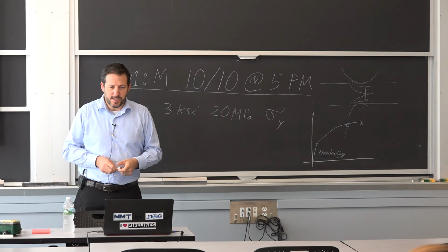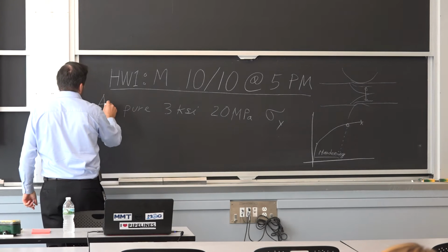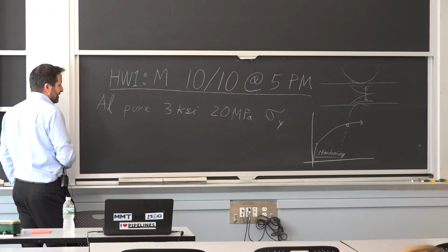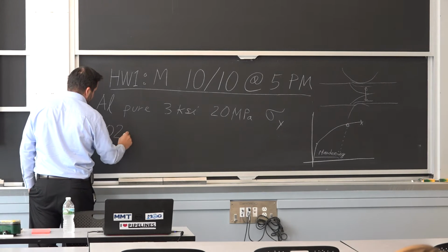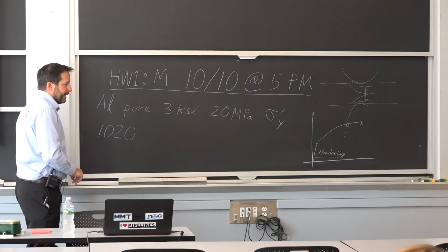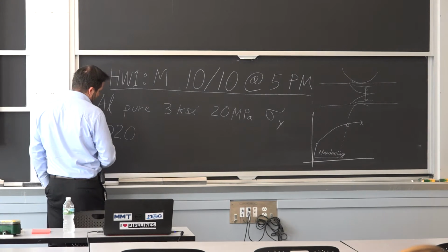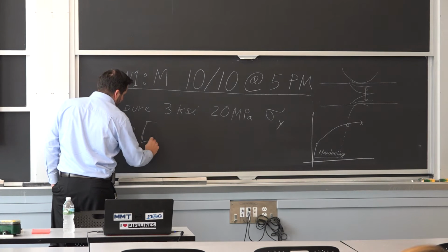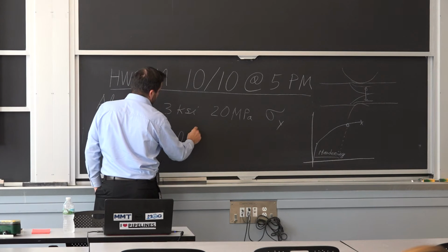So, that was the case of aluminum. If we're talking about relatively mild steel, and I don't want to go too crazy, but let's say this is a standard structural steel that you'll use in construction. So let's say I would start around 30 KSI.